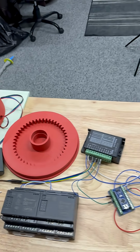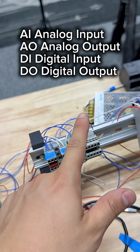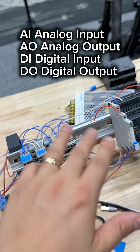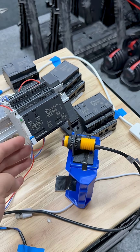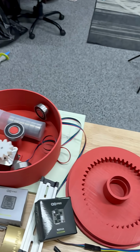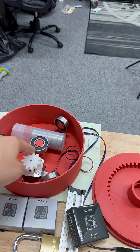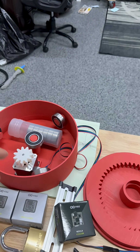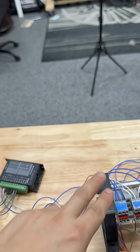Next up is a combo, so pay attention. AI, AO, DI, DO. Analog input, analog output, digital input, digital output. These are the four most common types of signal. Digital inputs mean on or off signals like on-off proximity sensors, while digital outputs mean things like on-off pumps. But analog outputs could be variable speed pumps or motors or control valves, and analog inputs are varying range things like temperature, pressure, flow, things like that.